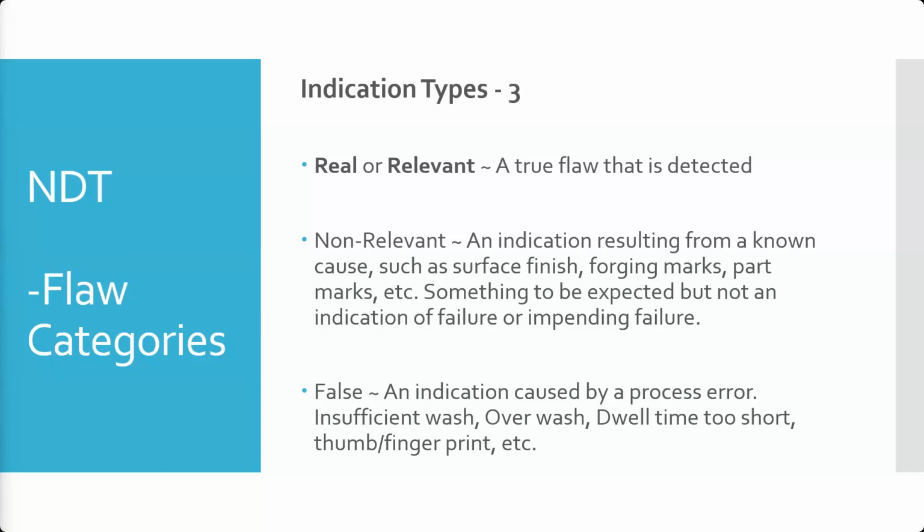to keep running. But if that crack had grown an inch or more during that time period, the fear is that by the next inspection, it would exceed that 2-inch range. And so that would be a failure. So in that case, if it was more than 2 inches, or if it had grown over a certain amount in a period of time, that case is no longer serviceable. That engine would have to be removed, and the turbine case would have to be changed.